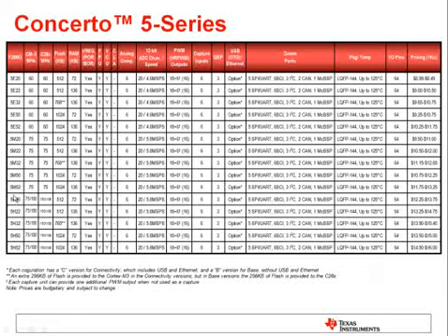For high level, these devices are actually capable of 2 different settings. It can run both at 100 MHz each, or there's the option to boost the C2000X speed up to 150 MHz. However, this will require the Cortex-M3 to be clocked down to a maximum of 75 MHz. And this is purely because of the clocking setup. This is decided by the customer when they initialize the device, that's why it's the same part number.